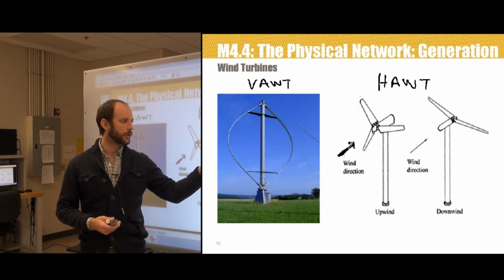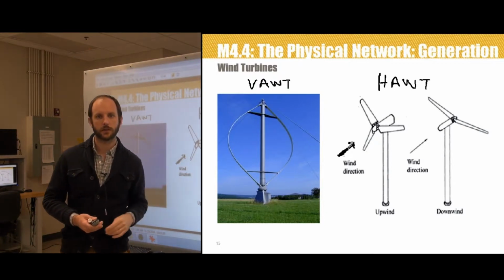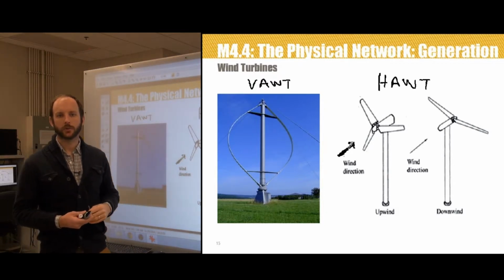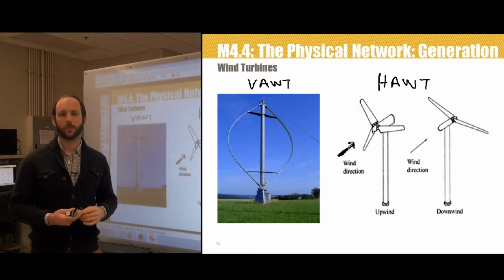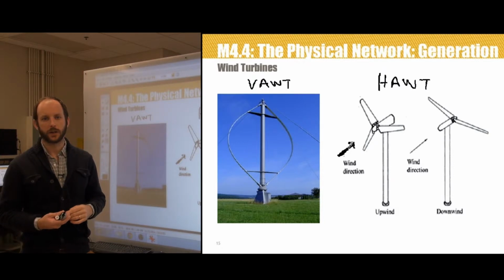A more important advantage of the downwind design is that the rotor can be made more flexible, because the bending direction is going to be away from the tower in this case. So this will reduce weight and will also take a significant part of the load off the tower when the blades bend in high winds.